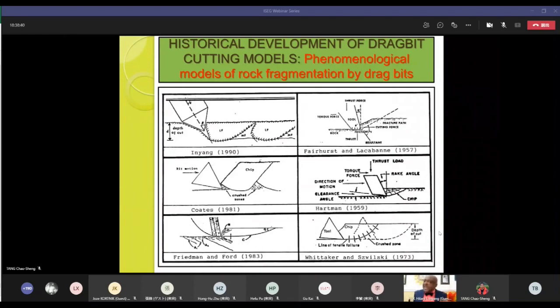So how do we then improve rock cutting? If we can have a system in which we can induce cracks in a material before this cutting bit acts on it, it means therefore that we can reduce the required cutting forces. We can also reduce the required cutting energy, and machines would be able to cut those trenches very fast in rock.